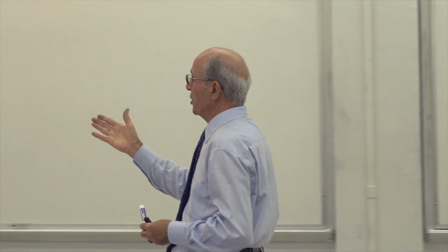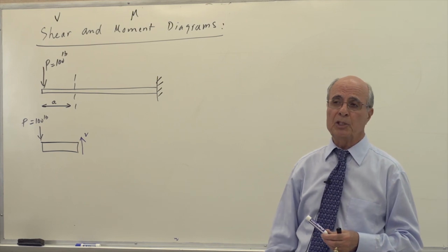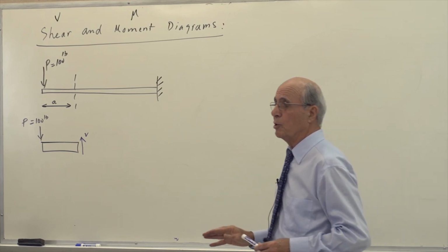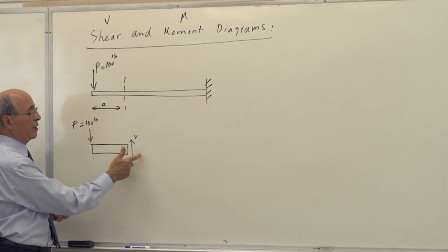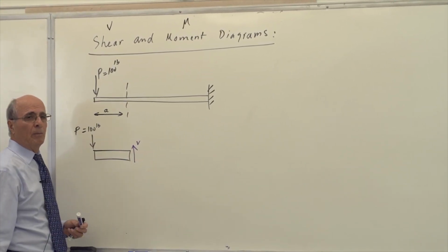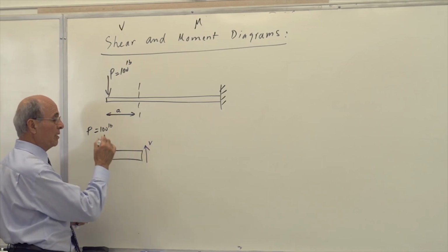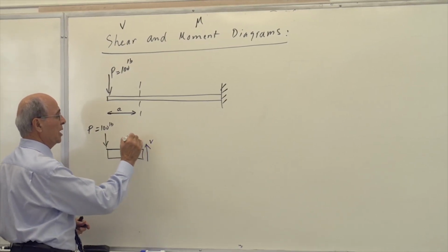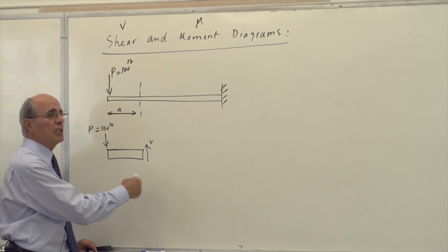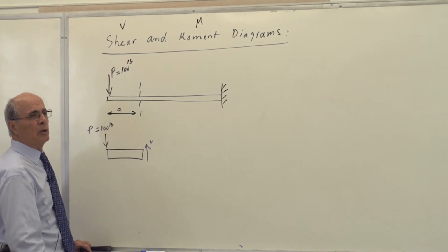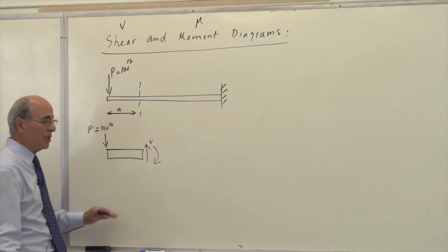Okay. Is this finished? Is this in equilibrium? No, of course, everybody should know that. If you know that, then you don't know your statics, because this is a couple. Everybody see that this is a couple, and therefore there should be a moment. Everybody knows that, so I'm going to assume. So the action is here. This is the first thing. The action is going to here. If you put it this way, it's wrong. Everybody understand that, because this system should be in equilibrium, so the action is going that way. The reaction should be like that. So this is the real one.